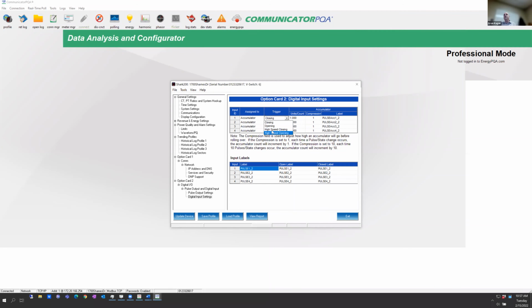And then we also have this feature for high-speed opening and closing. High-speed opening and closing is for gas and water meters. So over here, we have a pretty solid debouncing algorithm that when it sees the detector come in, we debounce it. But on water meters that are coming in very fast, we have to tighten up that debouncing, because you could be getting 100 pulses a second, 200 pulses a second. So we have a high-speed one where it has less aggressive debouncing on it.